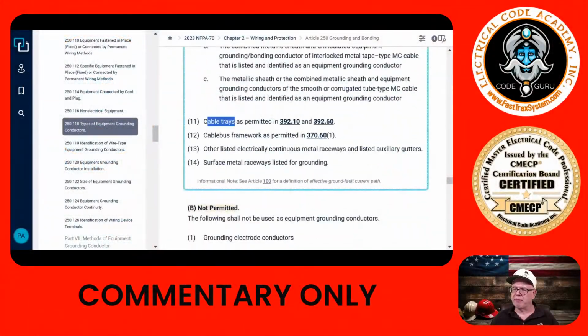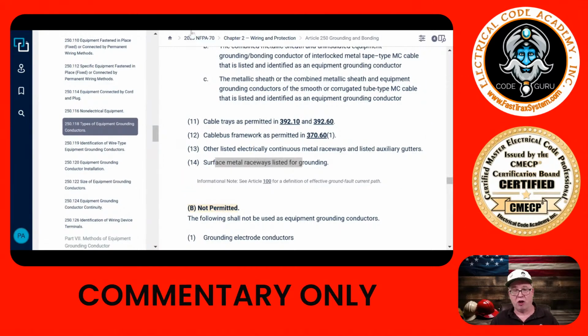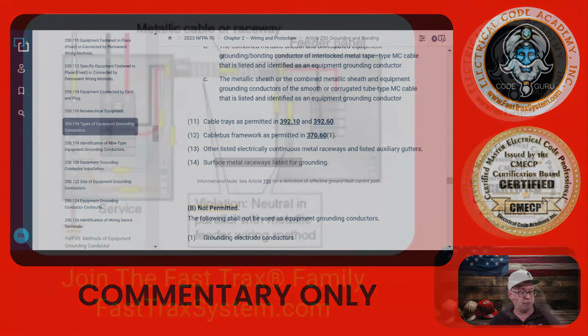Okay, so cable tray, that's obviously not what's in our drawing. And of course, cable tray has to meet these requirements as well. It has to be listed for use in grounding and bonding applications. They're out there, you just have to find them, but we don't have a cable tray in this image. And we certainly don't have a cable bus. We don't have anything like auxiliary gutters and things like that. And we're not talking about surface metal raceways. So absolutely not in this scenario.